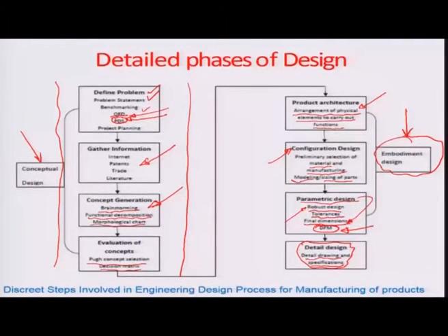And on the other hand, you are talking about a more well defined layout of the whole product, analysis of the functional requirements, and then trying to increase robustness through experiments or by setting up various evaluation parameters, so that the best design gets selected, which is laid out finally in terms of detailed dimensions and tolerances, and also evaluated from the aspect of manufacturability before setting up the final design into a process plan, or later on probably the subsequent manufacture.